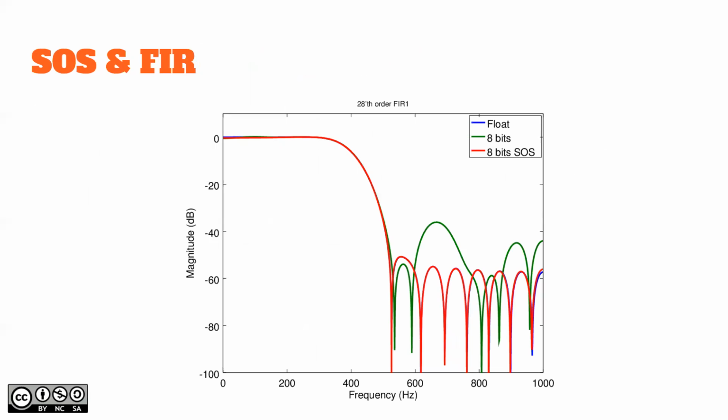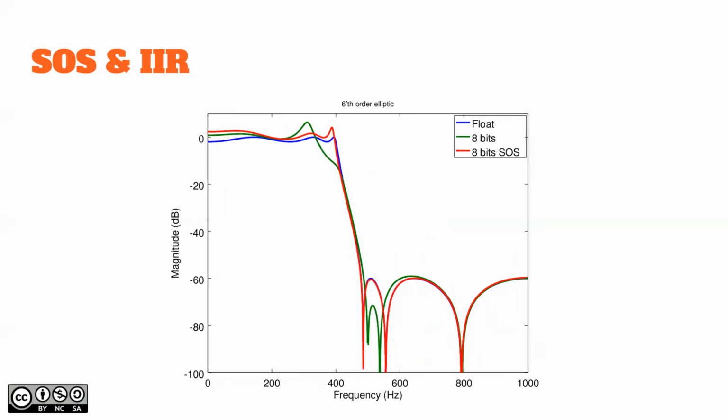Okay, on FIR it is okay. Usually the passband is okay, even when you start to quantize the filter coefficients, the stop band attenuation degrades. But when you go to second order systems, then you can get that fixed.